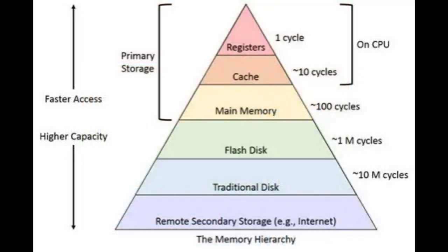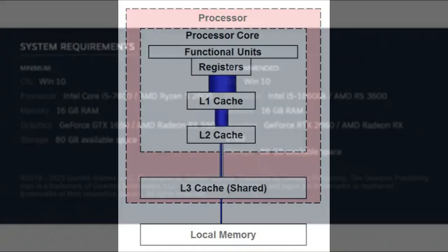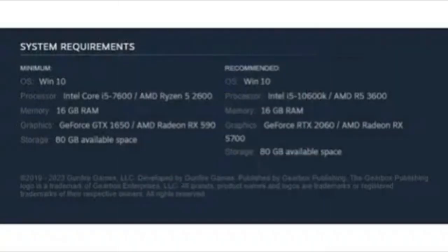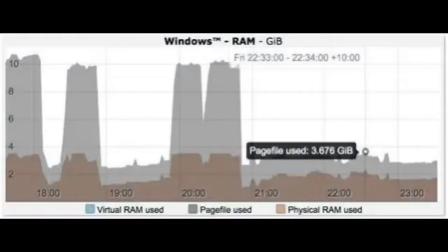Now, capacitors leak charge fast. Within milliseconds, a 1 would fade into a 0. To prevent data loss, the memory controller refreshes every cell thousands of times per second, typically every 64 milliseconds. This is why DRAM is called dynamic. It must be dynamically refreshed to keep data alive.